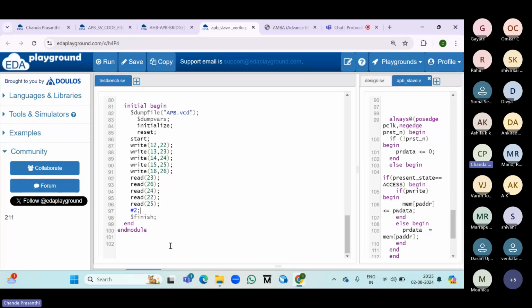See, the best practice is whenever, before I told you or not, I don't know. The best practice is whenever you are trying some SV program, if you want to implement a test bench in SystemVerilog, first write the design properly, check the compilation errors, any syntax errors or any runtime errors, check with the design first, and try to write a simple Verilog program for the design because you are in the practicing stage. Okay. Once you get the correct proper output with the Verilog test bench, then you can develop the SystemVerilog test bench.